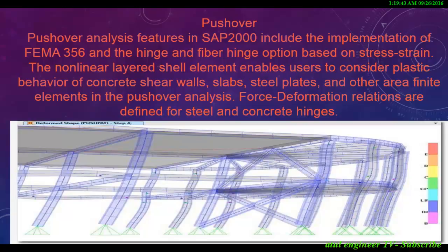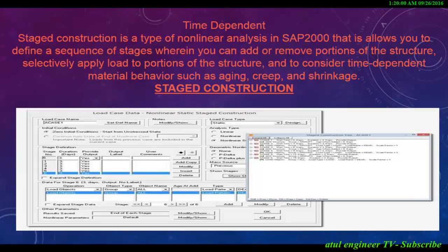Pushover. Pushover analysis features in SAP2000 include the implementation of FEMA 356 and the hinge and fiber hinge option based on stress-strain. The nonlinear layered shell element enables users to consider plastic behavior of concrete shear walls, slabs, steel plates, and other area finite elements in the pushover analysis. Force-deformation relations are defined for steel and concrete hinges.